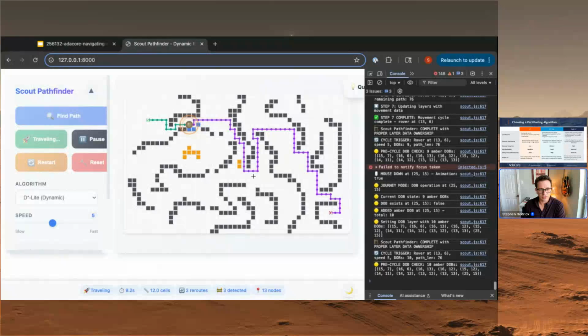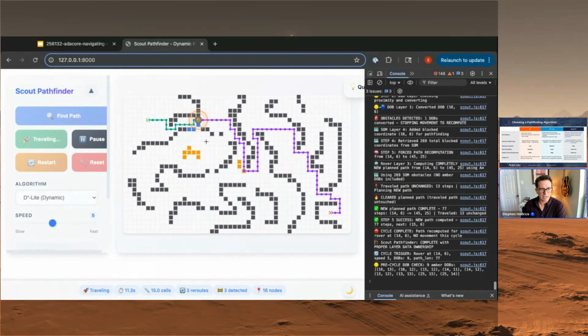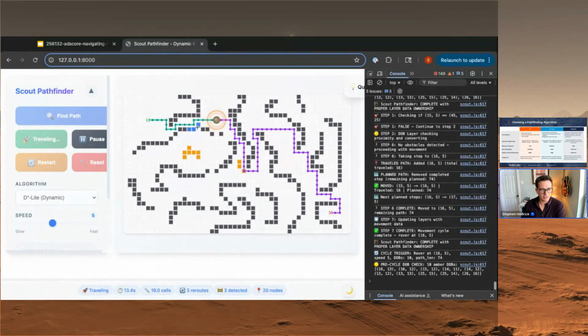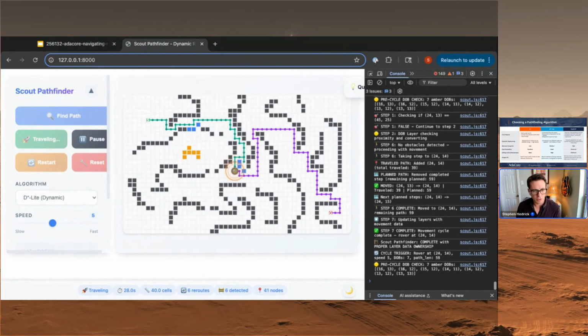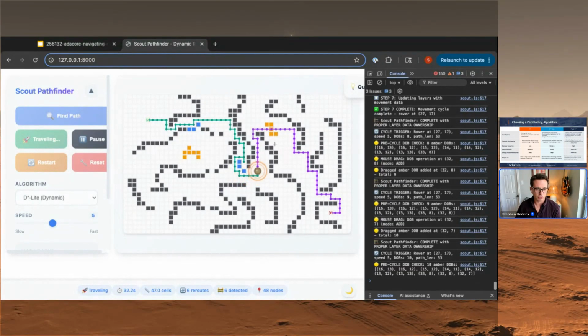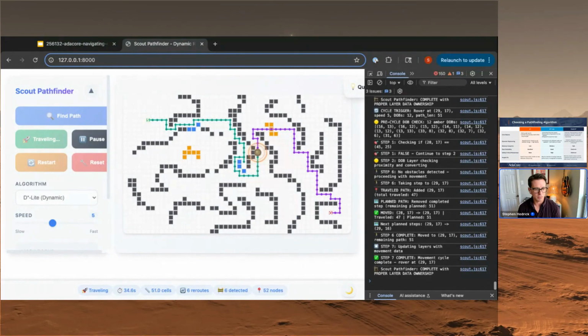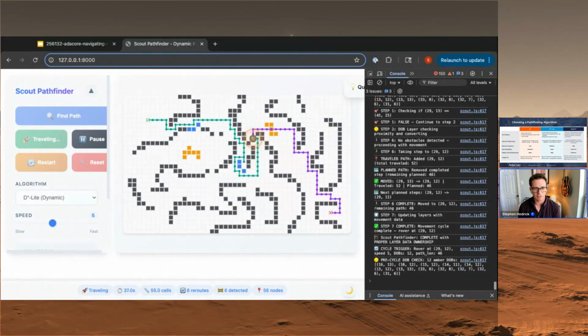As it moves along its path, you can see that as obstacles come into the circumference of its sensor, it will have to plan around them. The ones over here are not getting into that, and so they're not converting into something that it will need to plan around. And it will add these data points to a node list, and it's always referencing this updated node list, where these dynamic obstacles are converted into static obstacle blocks.